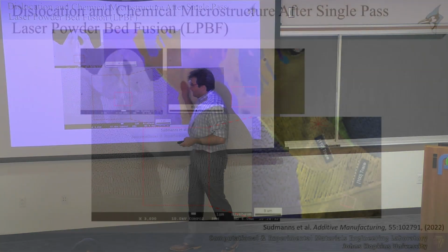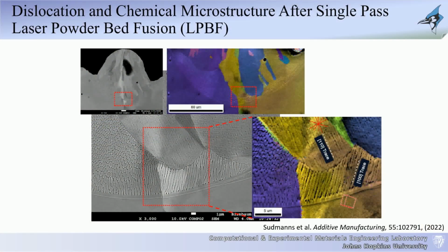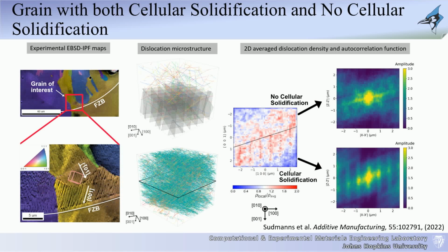There's a lot of intriguing physics that they have observed in an individual grain experimentally. This is one single grain. They've actually identified 2 different sets of traces, and they went in and identified that the chemical structure only is present in this lower half part of the grain. So you can build that into the simulations, and that's what we did. So again, the grid in the lower half here represents what they're seeing in the experiment. The chemical structure is only forming in 1/2 of the grain, where the other half is more homogeneous. You can run your dislocation dynamics. You get a spaghetti, do your analysis, look at different regions. In the lower half where you have these cells, you can potentially see the alignment. In the upper half, you don't necessarily see a very well alignment.